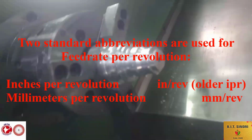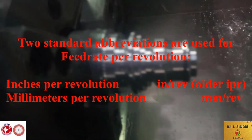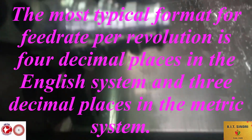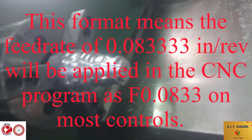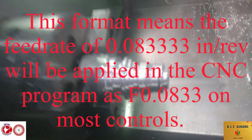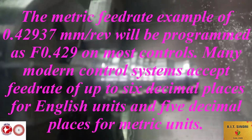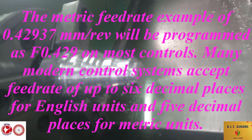Two standard abbreviations are used for feed rate per revolution: inch per revolution and millimeter per revolution. The most typical format for feed rate per revolution is 4 decimal places in the English system and 3 decimal places in the metric system. This format means the feed rate of 0.083333 inch per revolution will be applied in the CNC program as F0.0833 on most controls.